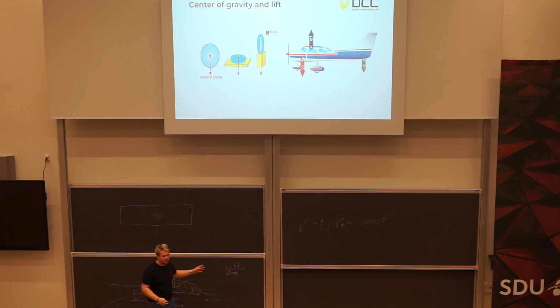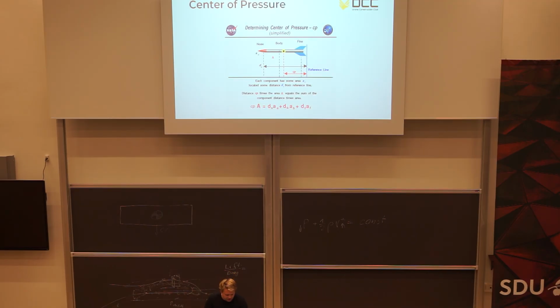So you have center of gravity, and you also have center of lift. Usually, if you want stable flight, you will have center of lift right around where center of gravity is. However, you have multiple wings on the airplane: the main wing, and then the control surfaces. They sum up, and for stable, coordinated flight you want all of them in the same spot. So those are the centers.